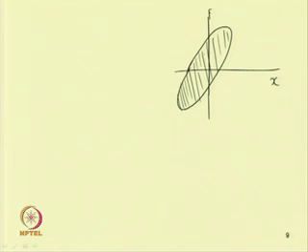So, now we know we can write different types of damping present in the system. They may be linear or nonlinear. For example, in case of linear damping, we have simple viscous damping. That is linear, and we have written the equation of motion in this form: m x double dot plus k x plus c x dot equal to 0.